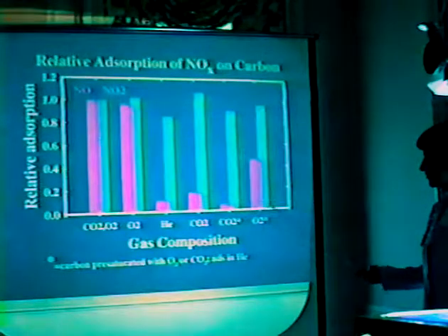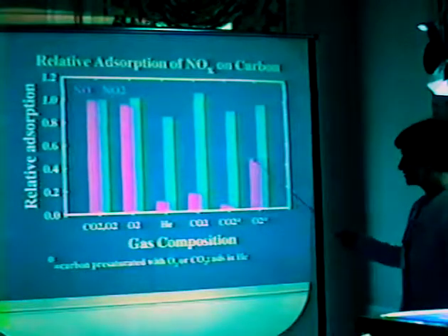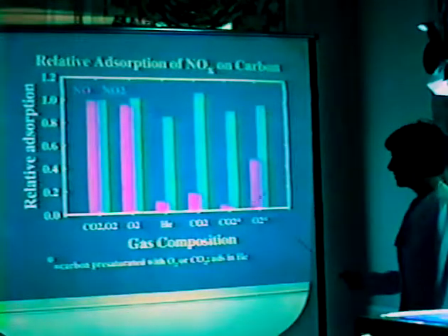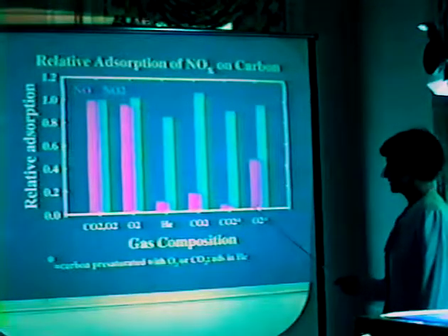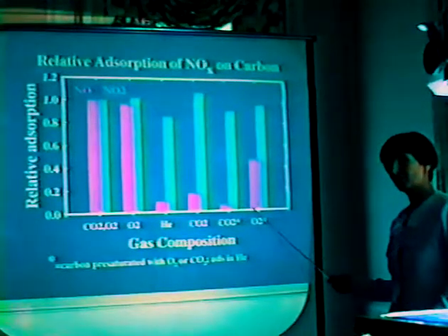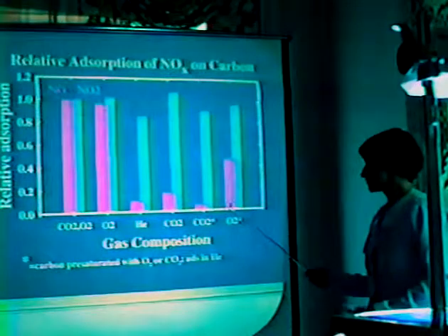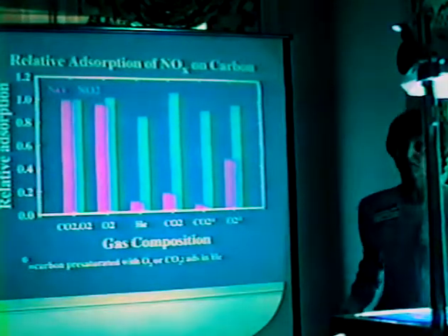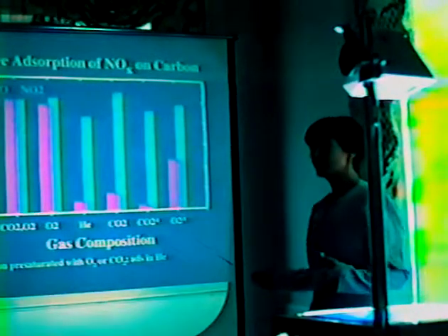This case here where we pre-saturated with oxygen and we get much better adsorption from the base case, we're not really sure. There's about a 0.5% increase in weight of the carbon with the pre-saturation of oxygen. However, it's very difficult to purge this rather large system of oxygen completely before adsorption.